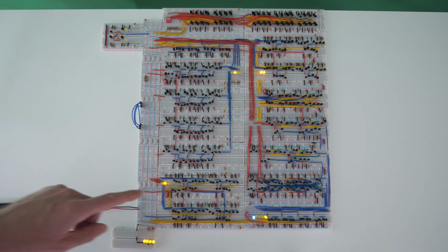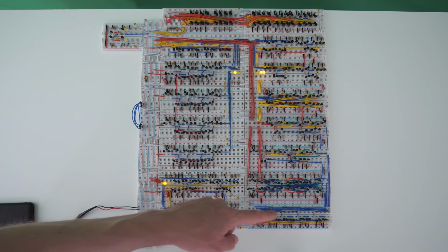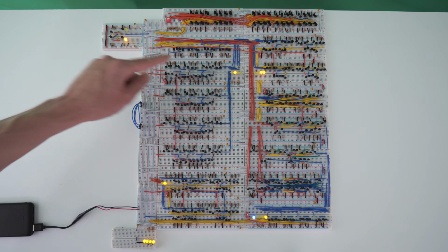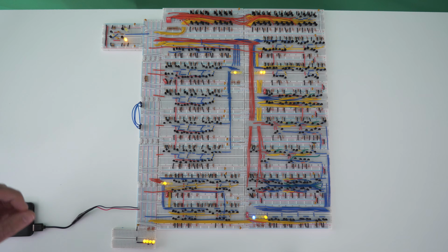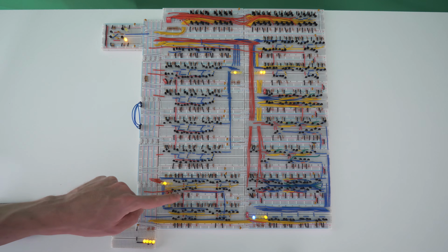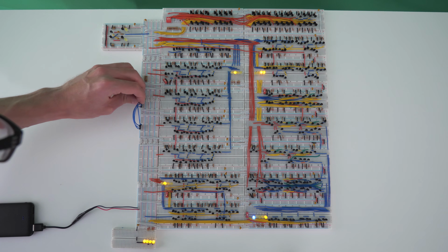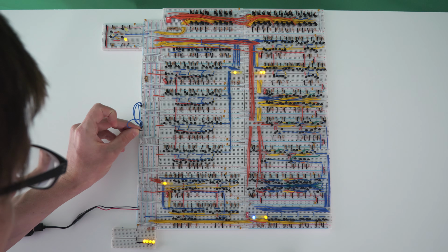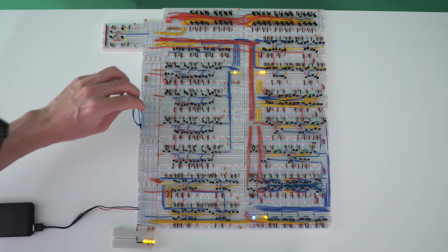Now, technically, we wouldn't have actually wanted to send the output directly into the output register from the output of the ALU. You would actually want to load it into the A register and then load it into the output register. So let's clear the value of the output register and do that last step that way. So we can actually clear the output register by just having the clear pin go to ground. So I'm going to connect clear to ground, which is actually this 4th pin right here. So now our output register is cleared.